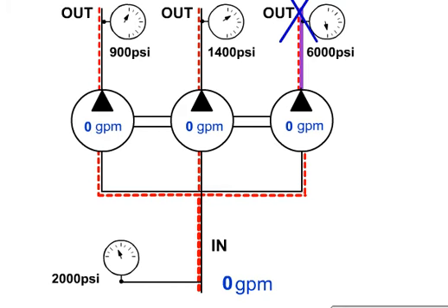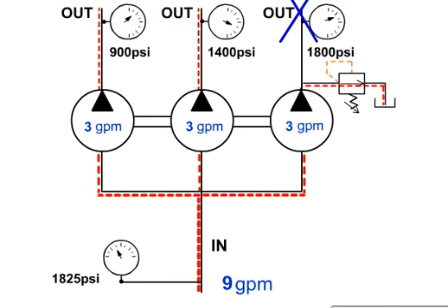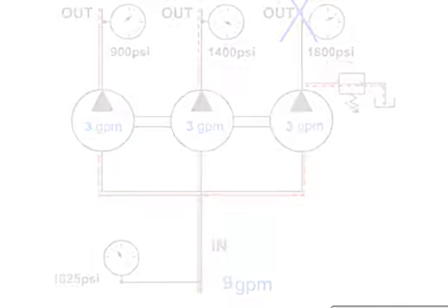Pressure intensifies in the circuit that is initially blocked. A relief valve placed in the circuits downstream of a proportional flow divider will prevent pressure intensification. The relief valve will also keep the flow divider from blocking flow to other circuits.